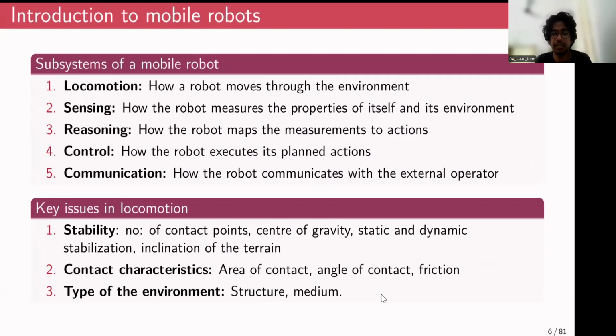Because if any one of these is a factor, you can observe that the table will always wobble, right? So at a point only three legs will be in contact. And the reason is that to define a line, you need only 2 points. To define a plane, you only need 3 points.